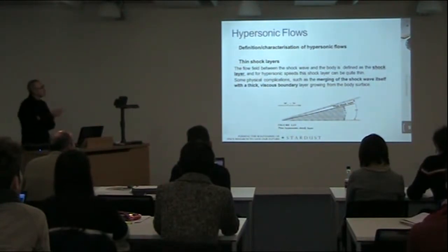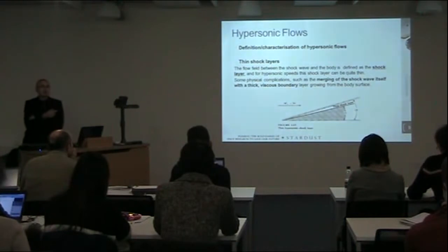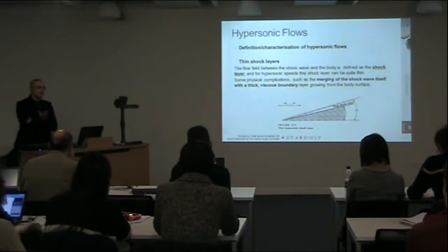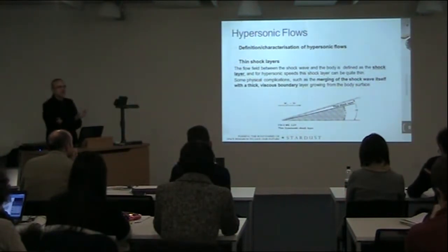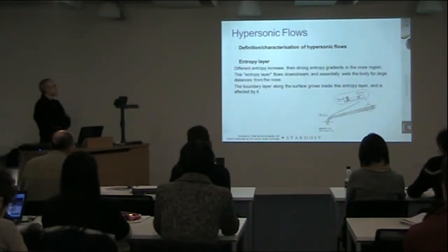And there could be an interaction between the boundary layer of the subsonic flow after the shock and the shock itself, which is one of the things that should be correctly modeled to characterize the flow.